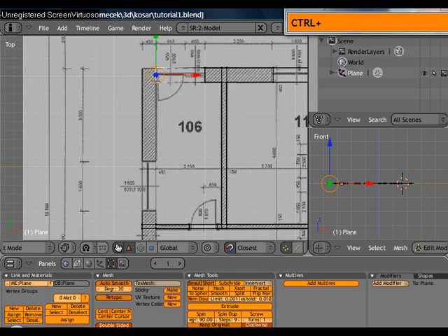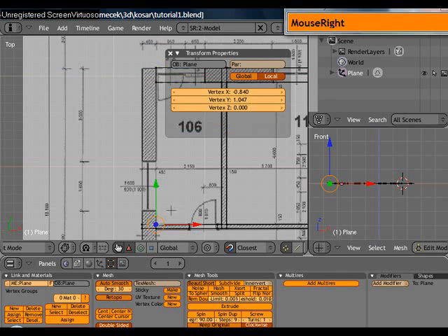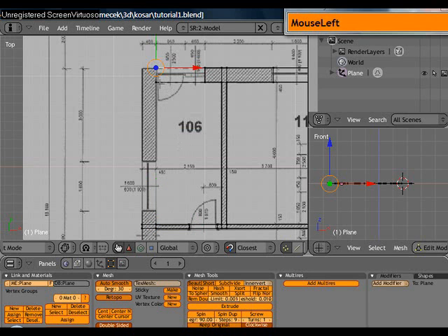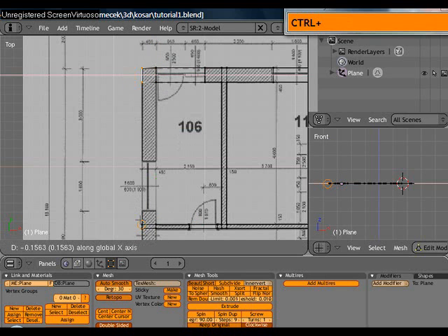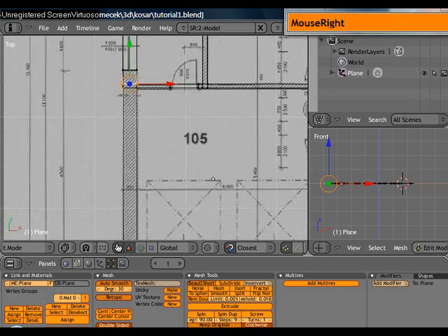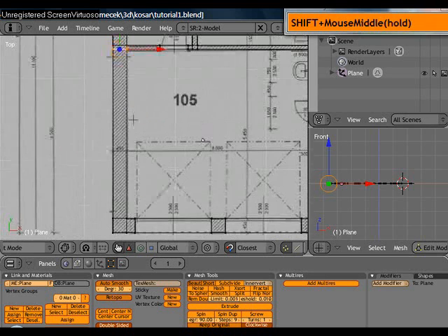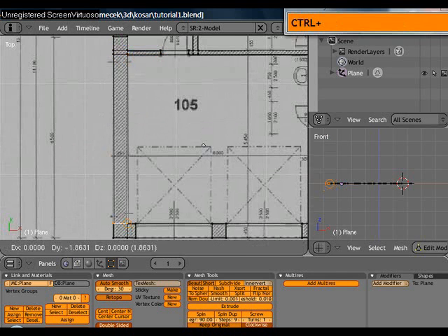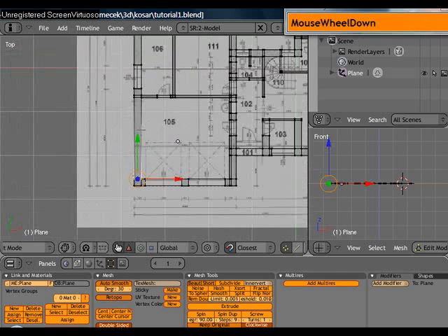So when I press N, I can check now that this is 840 and this is 840 as well. They're aligned. So I can now do it quickly with the rest. Extrude. I can go very quickly now and align. As you see, it's pretty quick. It just jumps right where I want it. And I can do the same with this one. There you go.